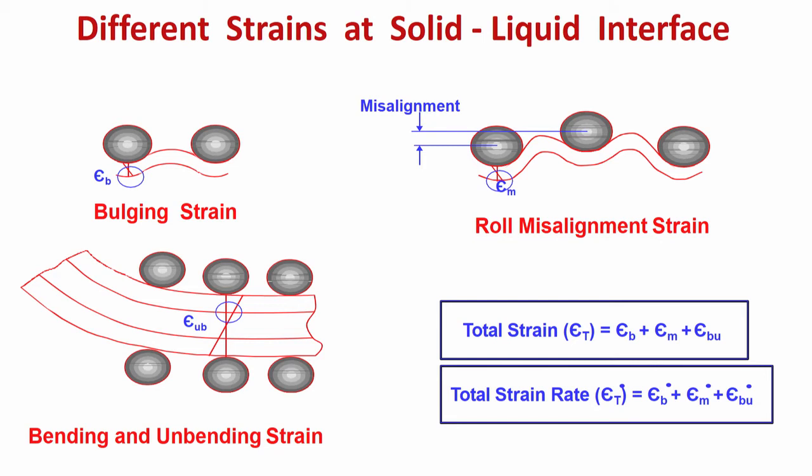Because the orientation of the rolls and the segments are getting changed, there is a stress generation on the strand. But as I have told you, it is not done suddenly. You have to give a slow orientation change in the direction, so that the amount of strain is less. Nevertheless, there will be some strain. So, that is called bending strain.